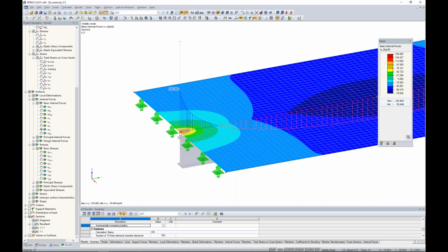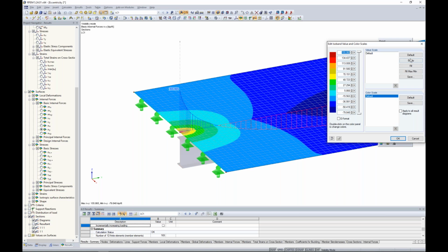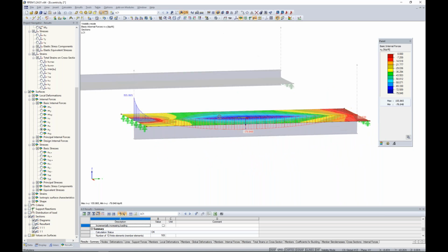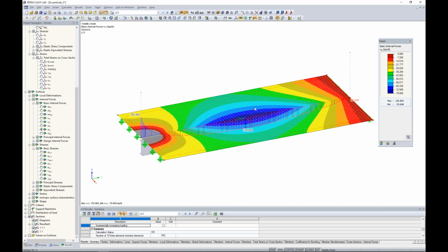So we could probably use an average region, maybe rigid links, to take care of that. In our control panel, maybe we completely take out tension and adjust the control panel to look only at the compression forces. And it's really as we'd expect. We want this slab element to take those compression forces from this applied area load.